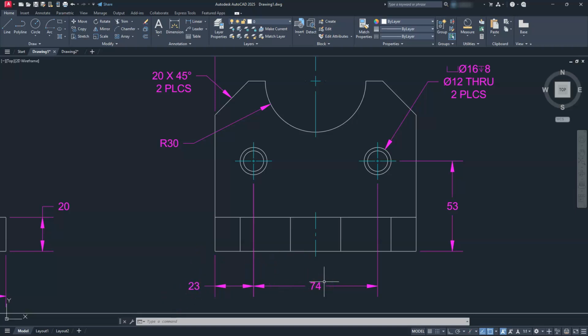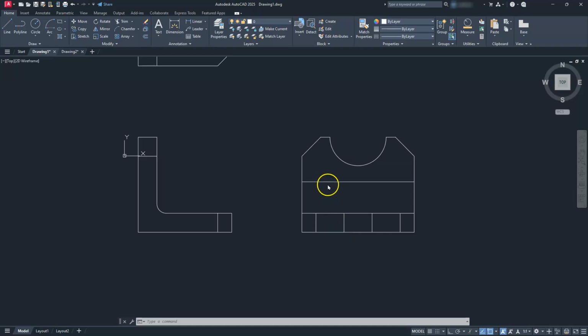Now, I could have also shown you a way to do them just by one step. But a lot of times, especially if you're beginning to use AutoCAD, it's always good to go ahead and make these reference lines. That way you're just snapping to intersections and endpoints and things of that nature. So let's go to the offset command.